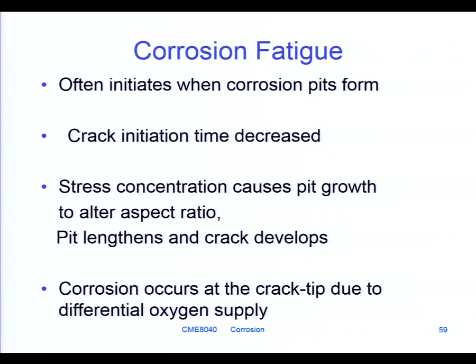and maybe it's just a gut feeling, I'm not sure whether I've got any evidence for it, that you more commonly get pitting and then a fatigue crack in corrosion fatigue, whereas in stress corrosion you quite often get no pitting and you get a crack. So there's a slight difference in the mechanism in that sense.